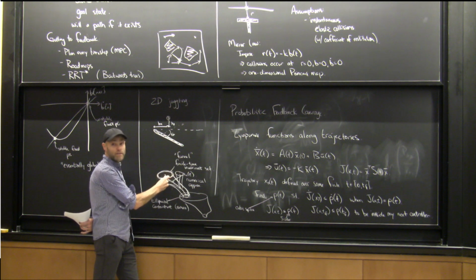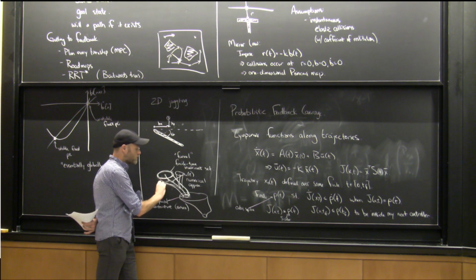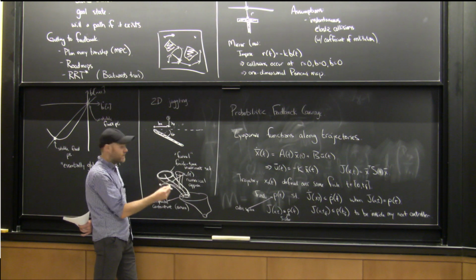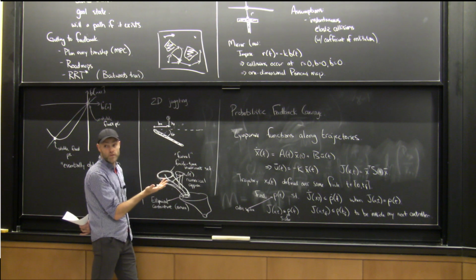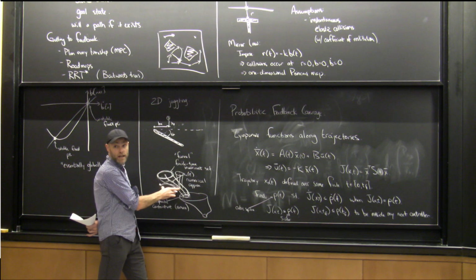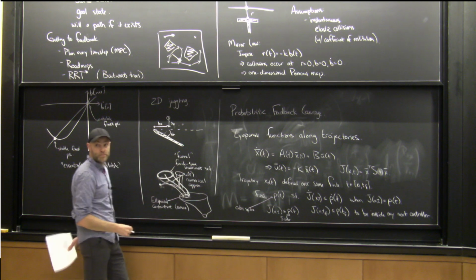It'll change the size of my funnel, but this is somehow a more fundamental object for reasoning about uncertain systems. That's a great question. But I agree that this recipe of just connecting with trajectory optimization up and down the tree works even if you don't have funnels, and it actually works fairly well. It's just you pay a large price for calling SNOPT every time you add an edge. So it works best, in my opinion, when you have only a sparse tree because of the funnels.